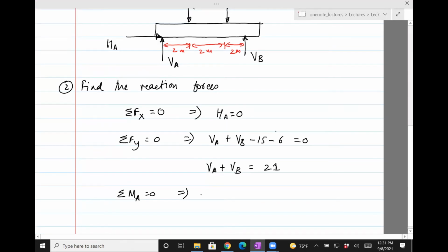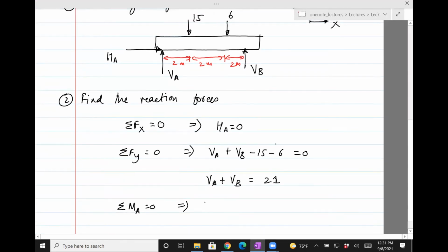So let's write the moment due to the force of 15 kilonewtons. I'm going to skip the units. I should have written 15,000, but I just skipped the kilonewton. Remember that the forces which will come out of this are going to be in kilonewtons. So 15 is acting in the direction shown about point A. It'll induce a moment which is clockwise, as shown. Clockwise is negative. So negative 15 times 2, 2 being the distance from A.